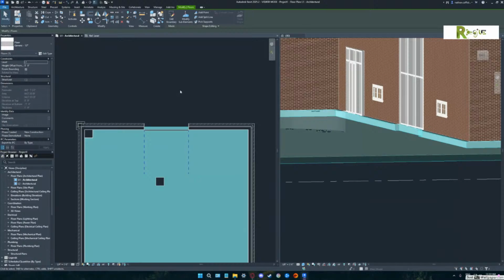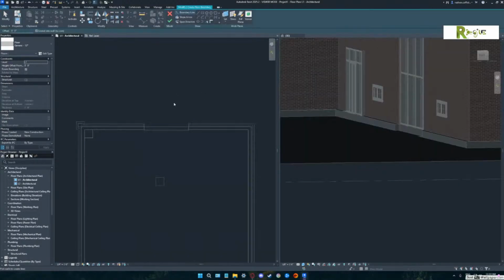But to answer your question about where you're going with that floor slab, it actually went to the face of the structure. When you picked floor, if you go back and pick, notice at the top where I told you to always watch. Do you see what it says? Extend into wall. That's kind of what I was explaining to you, and the reason you're not seeing that.